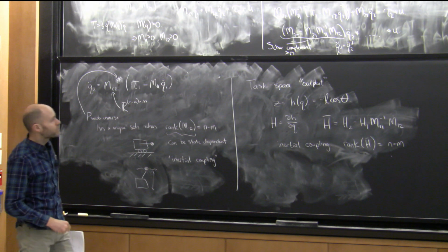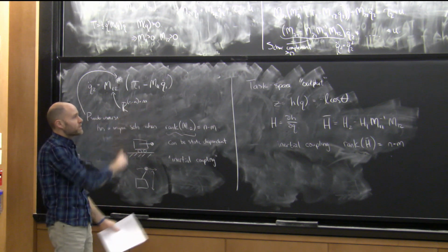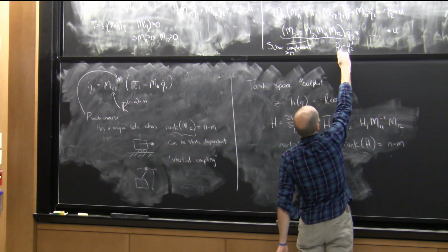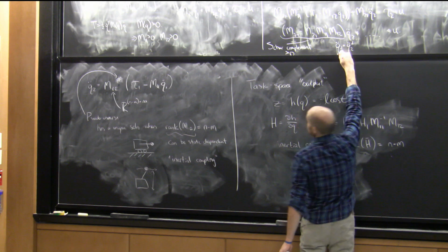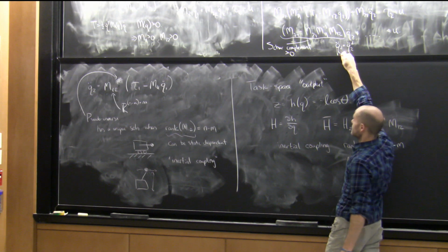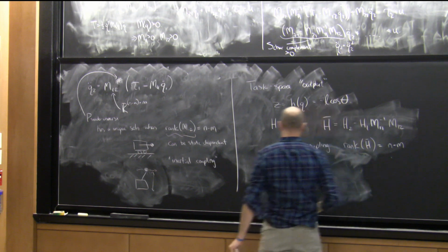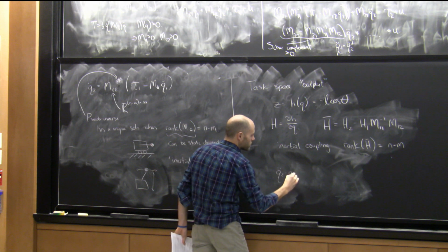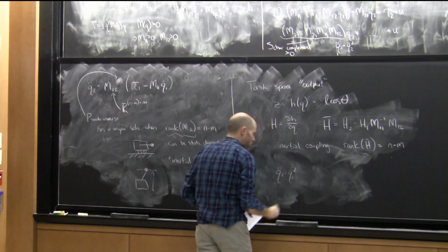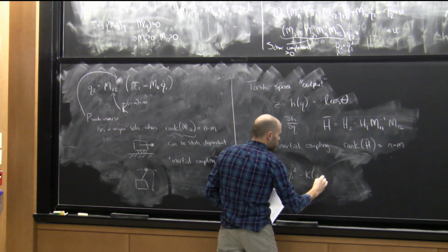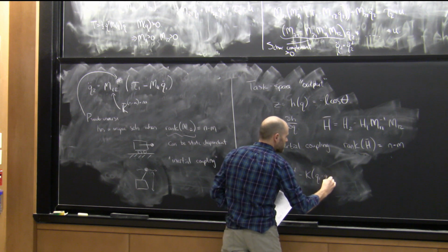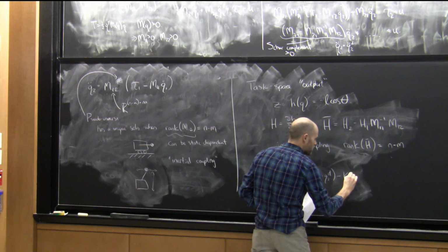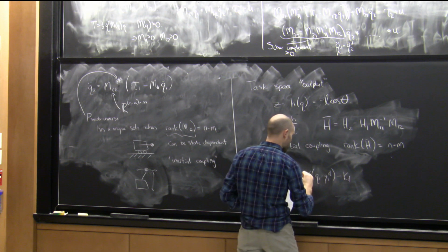Similarly, in our partial feedback linearization, I can pick things like this to insert the dynamics to be exactly that. I can also add stabilizing terms if I'd like, right? So maybe a slightly better choice of that would be to choose q2 double dot equals q2 double dot desired, minus some q2 minus q2 desired, minus, I flipped my signs here, but.